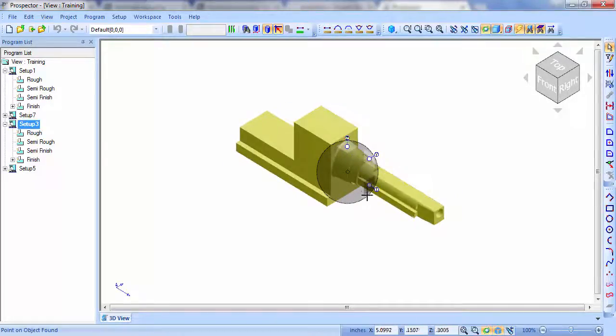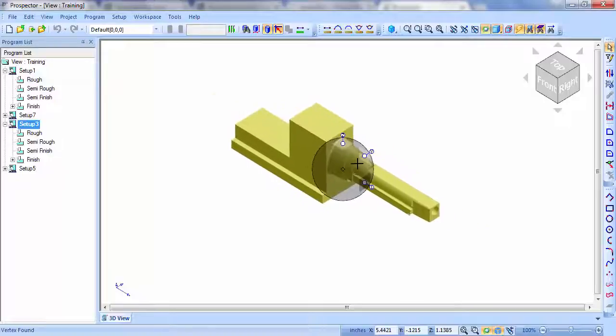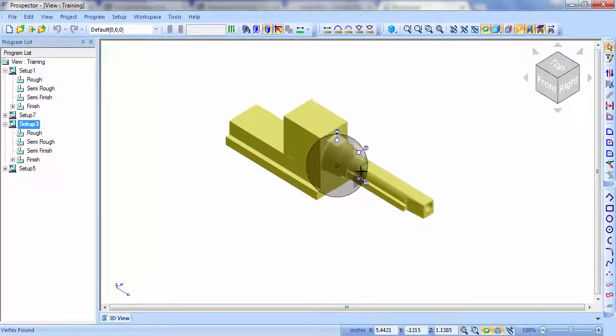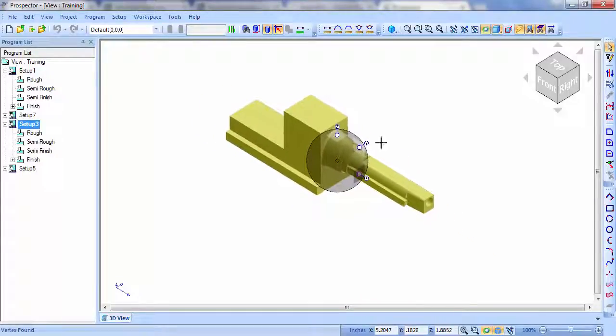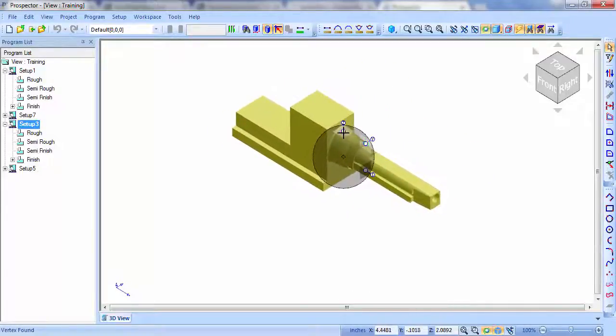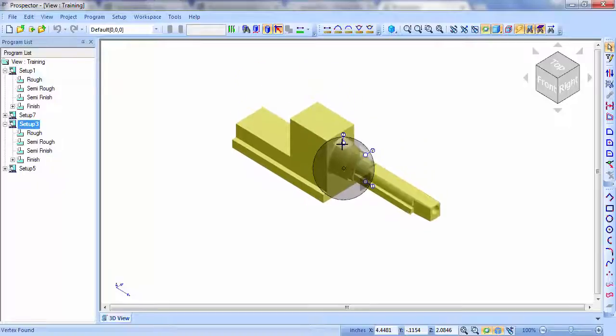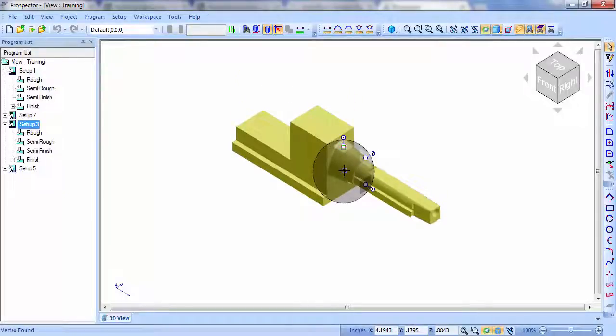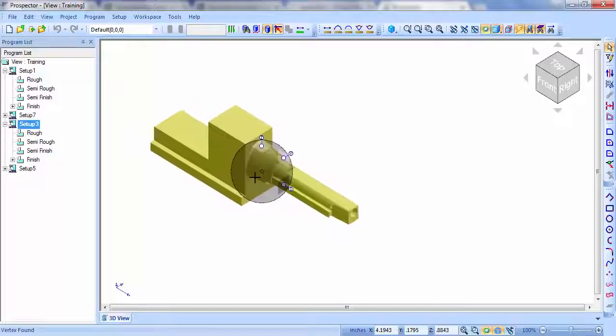If I right-click and hold on the base of the axis and then move the cursor parallel to the axis, I can pan along that. So again, it's just limiting the panning along the axis, X, Y, or Z. The last small hotspot is the center circle, a little diamond actually, that when I right-click and hold, now I'm just panning anywhere.